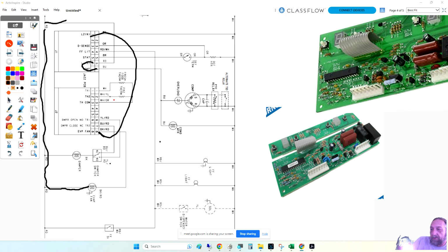I'm gonna stop sharing for a second. So here it is. And before class, I was trying to do it on the washer, but I didn't have time to mess with it. So what you do is you hook this into the 2 eyelets of the spring, and it's got little hooks on it on the very end. And then when you go ahead and you rotate this, it'll stretch the spring for you and hold it in that position. And then when you want to put it back on the washer, it's already stretched out to the position you want. You just put it on the washer and you tighten this up.